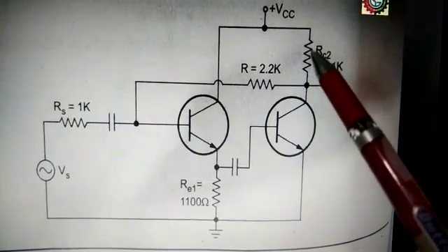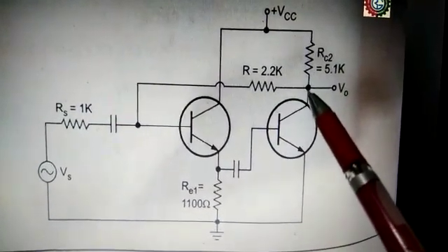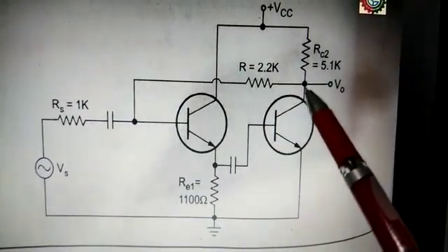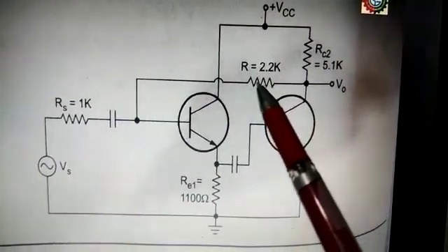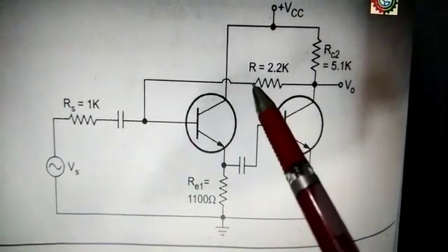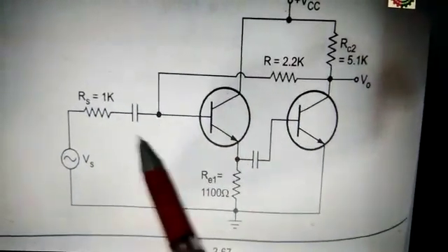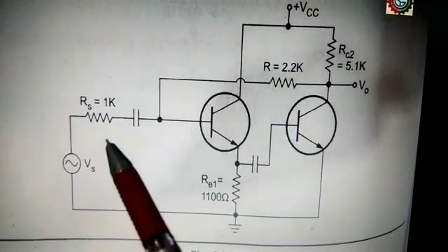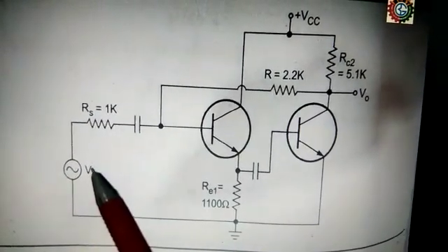The output voltage is the input to the feedback circuit, and it produces the feedback current IF, which is the output of the feedback circuit. This current is in parallel with the current source formed by the voltage source and resistance, that is the Norton equivalent.